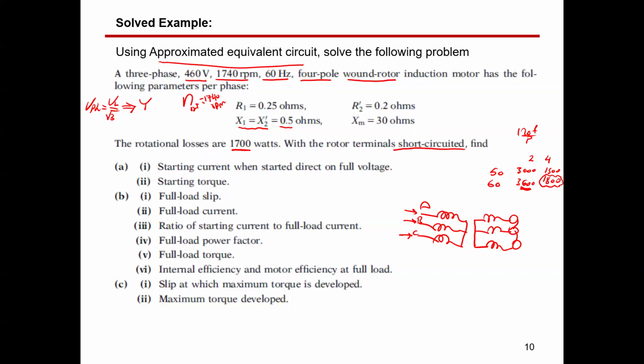So this has to be clear, guys. Short-circuited here means it's just closed in order to allow the motor to start. It doesn't mean there is a short circuit on the motor or a fault in the motor, okay?